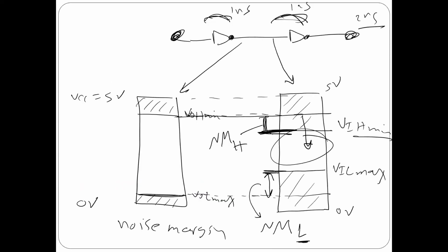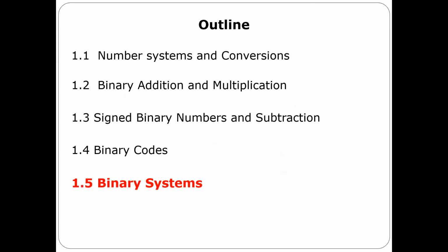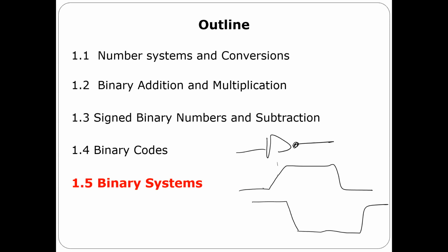I think there is another question I want you to think about. It's about what we call the maximum operating frequency in a logic circuit. There is a maximum frequency you can use. You get what I'm saying? This maximum frequency is related to tPHL and tPLH. I'm going to tell you quickly what I mean exactly. I told you, for this output to change, if I have an input this way, it's going to take some time until the output here responds. So there is some delay here, as I told you.